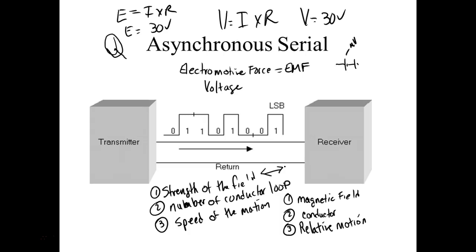But we run up with a problem: what do I have right here? Well, anytime I have a voltage, I have current. And what I'm doing is constantly changing the magnetic field. So if I got another serial wire next to this, it's going to try to induce a voltage into that wire. We call it crosstalk. If you're in communication, you talk about it, and you actually pick it up sometimes. You know, you pick up multiple.